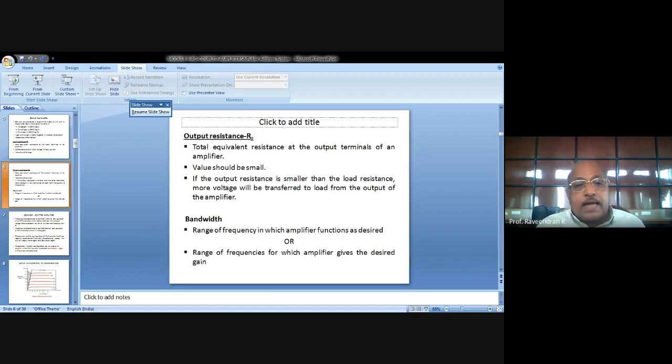And sometimes, depending upon the quality of the components used, meaning active components like transistors, capacitors, and resistors, if there is a leakage in capacitance, or certain leakage in the resistance due to continuous use or aging, then the noise level of the amplifier will be large. So the amplifier output will be noisy.